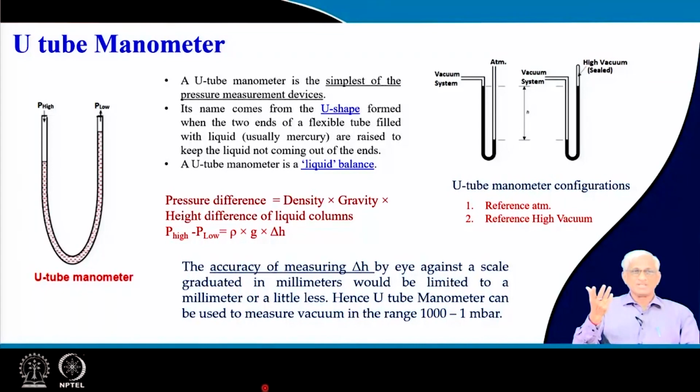The best way of measuring vacuum is the U-tube. Why? The U-tube measures in a fundamental way. If there is a pressure difference in a U-tube having mercury, the higher pressure automatically pushes down, otherwise Pascal will be unhappy, and automatically the levels will be different. It is nature's law.